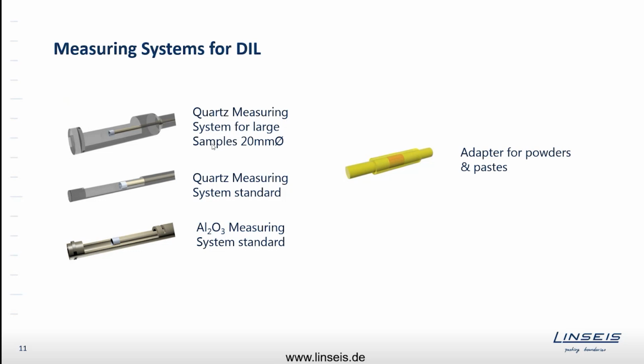You need to know that quartz and glass systems are very user-friendly again, because they do not show very much own expansion, so you can use them as they are. For all other systems, you need proper correction curves. You need to run curves with the system without sample to get an idea how much the system itself will expand and behave under the corresponding temperature profile. Otherwise, you will have a measurement error. With quartz and glass systems, you do not need to do that, because the expansion of the glass is so small that you more or less can ignore it.